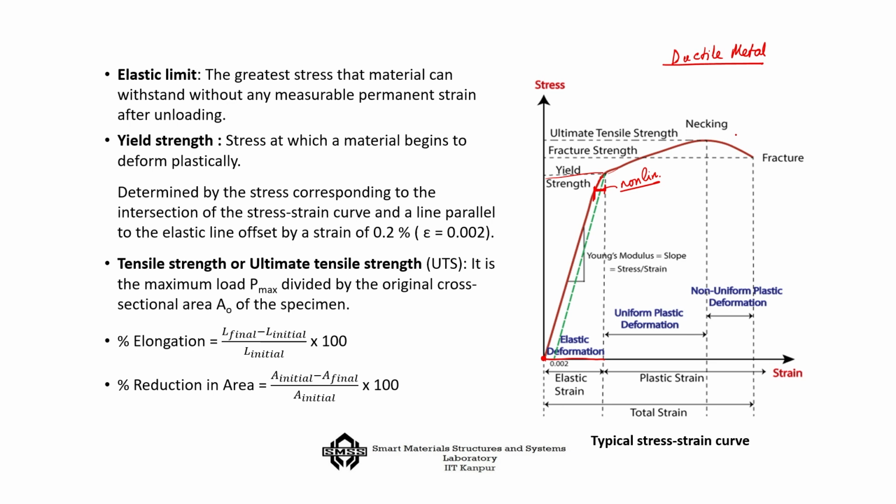Okay. So, here the significance is that if you take your load beyond this level, then actually two things can happen. One is that for brittle materials there can be a fracture that can happen. Okay. Whereas, for most of the other materials it may still deform for a little longer, and that is entirely inside the plastic strain domain, until and unless the necking starts to happen.